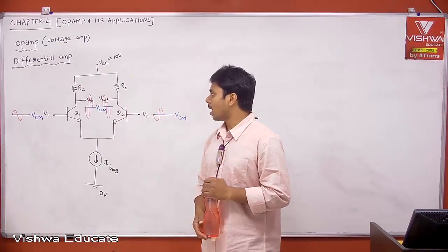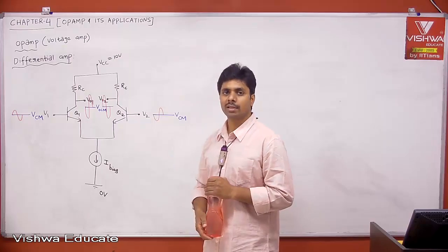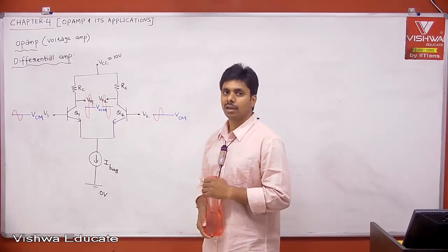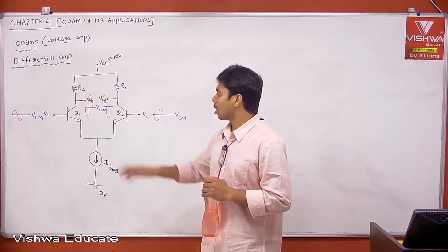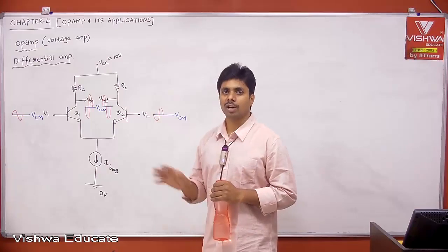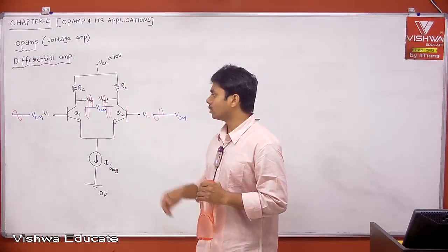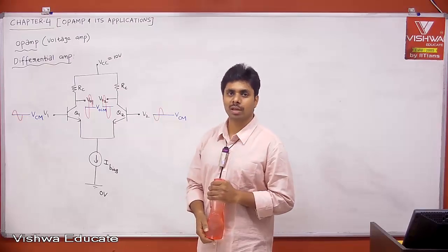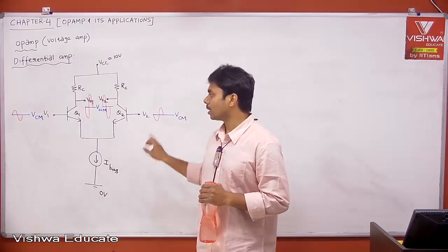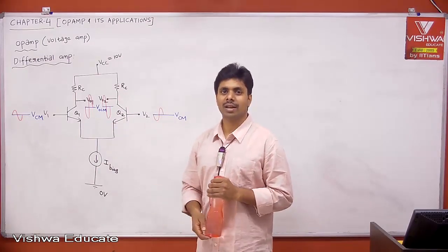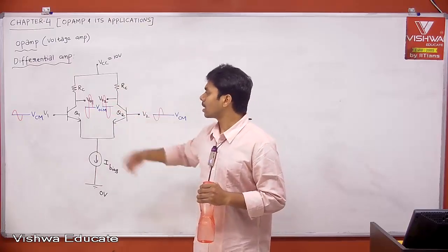trying to explain. I told that it is defined with two gains: number one, common mode gain, number two, differential gain. Common mode gain to be 0 means I don't want to amplify common mode signals, the signals which are common for both the inputs. That is what is a common mode signal, including the bias voltage, noise voltage, right, and power supply or any coupling.